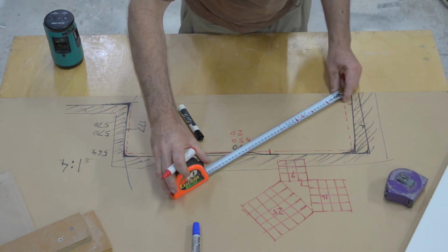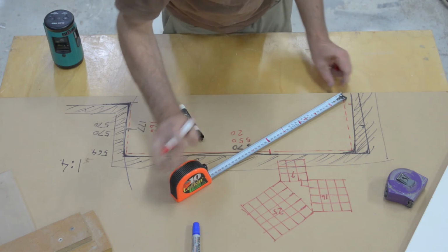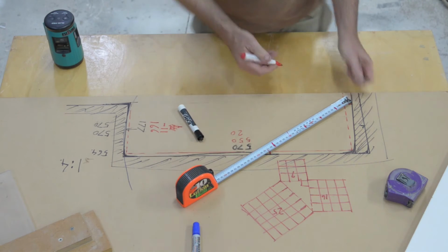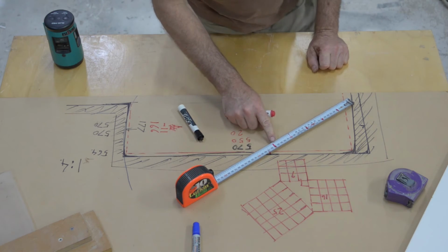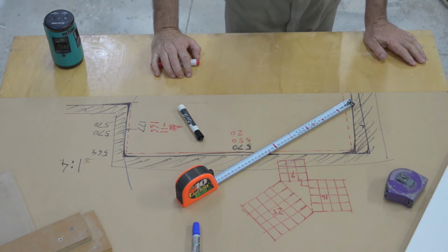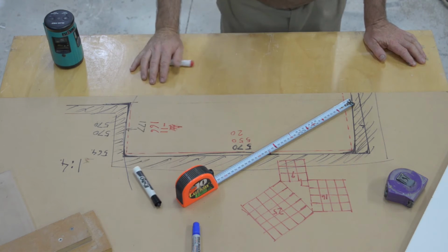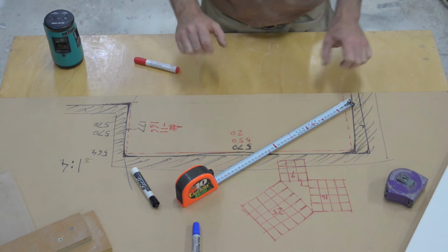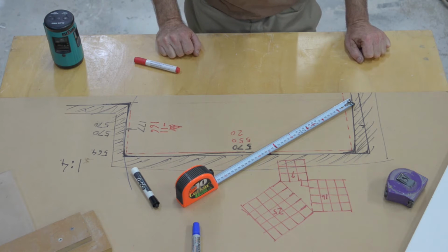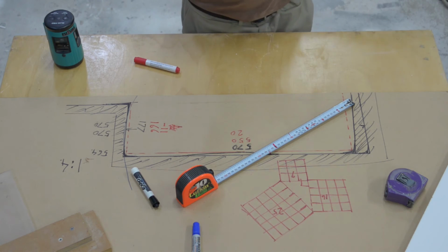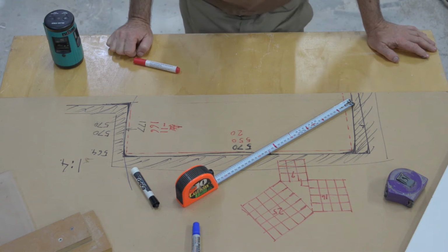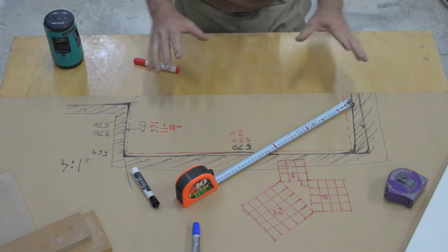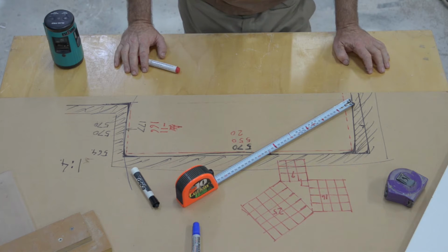Now what's our diagonal? It should be 25 centimetres or 250 millimetres, and it isn't. It's a much greater distance. It's 273 millimeters. So it should be 250, and we end up with 273. Now with all of these measurements, you're not aiming to perfect the building site, you're aiming to collect enough information to make a facsimile that you can replicate where you're going to do the manufacture. Or if you're going to use a CAD program, you want to be able to create a good facsimile of the site in the CAD system. Then you can actually build the design of whatever's going to fit in that space.